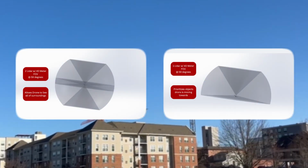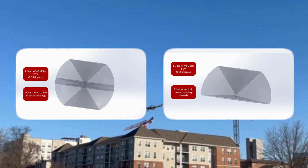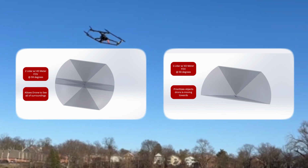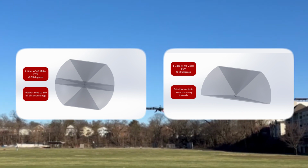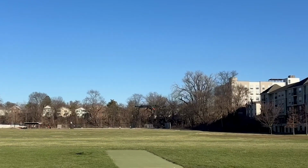Another design choice made was the number of LiDARs on the drone. We initially planned to have 2 LiDARs on the drone to maximize FOV, which would be especially effective at detecting obstacles approaching from the rear. However, due to weight concerns and complexity of integrating 2 LiDARs into our system, we decided to only keep the top-plate LiDAR, as forward-facing obstacles were expected to be a greater threat in the competition.